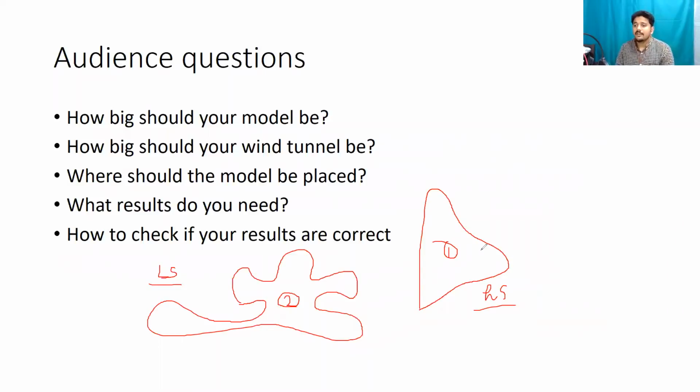In which case is it case number 1 or case number 2? When do you have to consider wind speed to do something more realistic? Would it be case 1 or case 2? It would be case 2, exactly, because in case 2 wind speed is definitely lower, right? Wind speed is always going to be lower than the speed at which the F1 car travels. But only in case number 2, your speeds are actually so low that your wind speed might affect your aerodynamic performance. But again, you don't have to consider it. But if you have to do your simulation accurately, that is a factor or input that you need to consider.